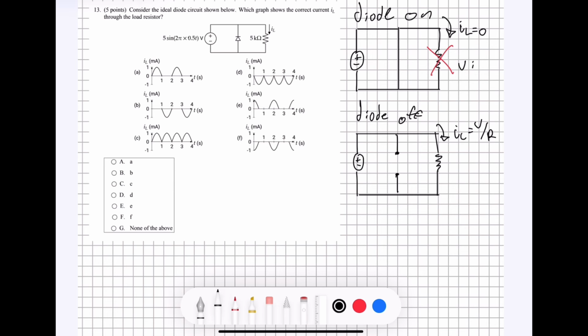So V is positive. When the voltage is negative, essentially this has become switched like that. We're going to see that the current will be flowing in like this and then like this, which is of course opposing the direction of the diode, because the diode originally would be like this. If the current was flowing like that, that's the opposite direction. That's what's going to turn the diode off. So we know that V has to be negative when the diode is off.